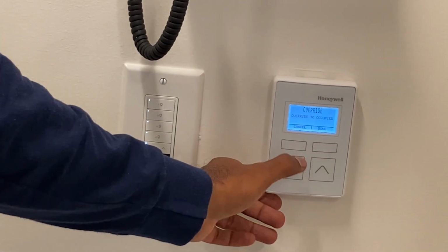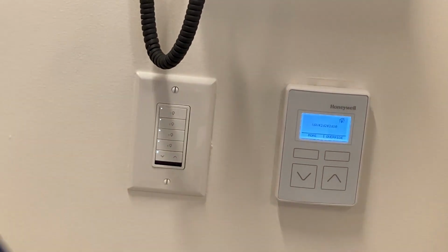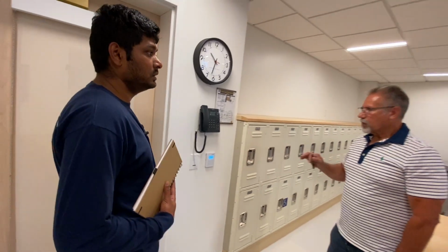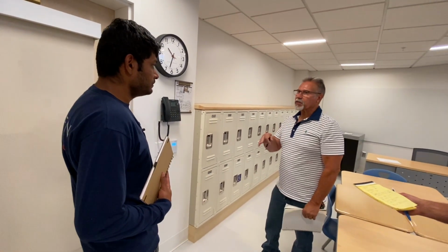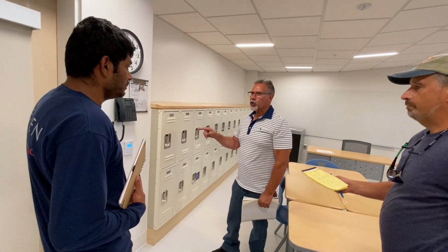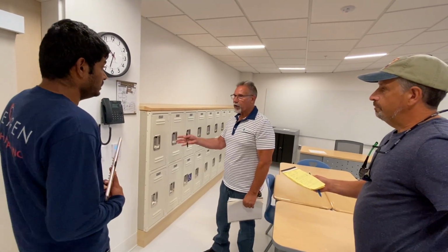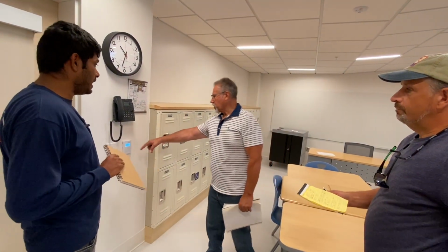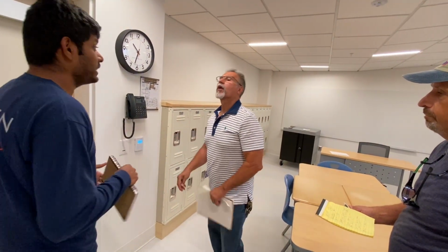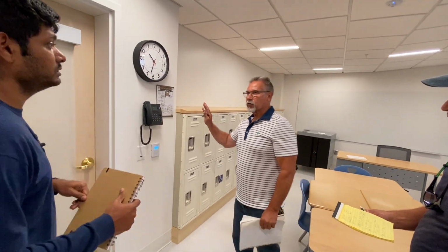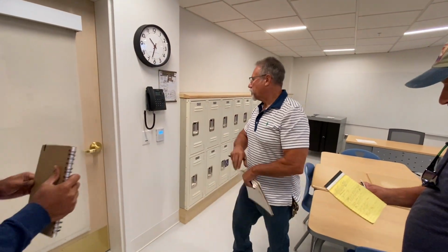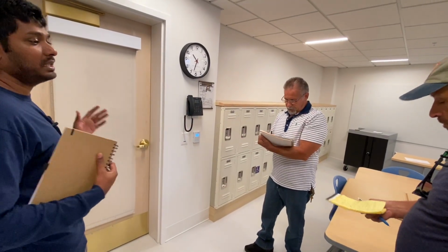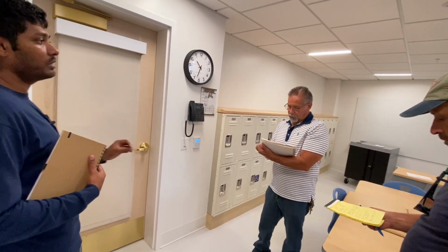So what are the teachers going to be able to do here? They can change the set point. They can do an occupancy override. It'd be nice if they can't do anything else besides that, because if somebody starts going in and changing things like humidity settings and whatever. So they have no access to change anything else. I just saw the humidity sensor come up. That's a reading value. So the only thing they can do is temperature and occupancy. Yes. The CO2 is read only, the humidity is read only, and the only writable points are the set point and the occupancy override.